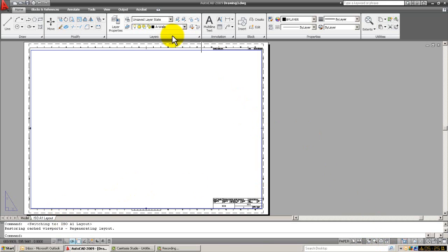So there's the template. Just note, as I said, this is in paper space, so this is like what you would see on a plan. Now if you click this little tab down here and flick that to model space, you'll see the bright blue line in there, and that is model space. That's the same model space that you're viewing over here, but just the section of it that you can see through that viewport. So you can scale things up and down inside that viewport to get them how you want them on the plan and at the right scale and what have you. So let's just go back to paper space. So there you are there.